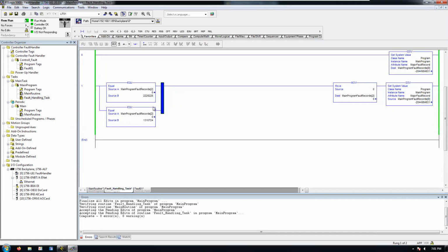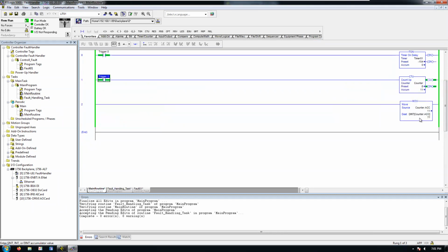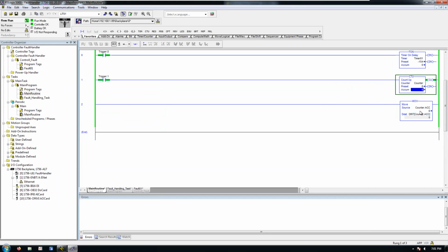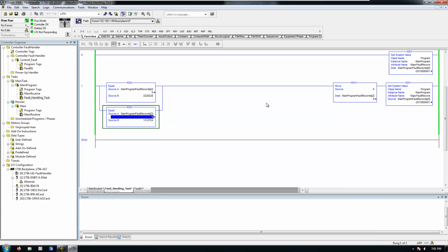If we were to look at this value, if we could see it, it would very quickly be cycling between probably both of these since they're both active faults at the moment. This one's trying to write to a non-existent set point. If we clear this, that fault will clear. Or if we turn both of these off, it will clear.